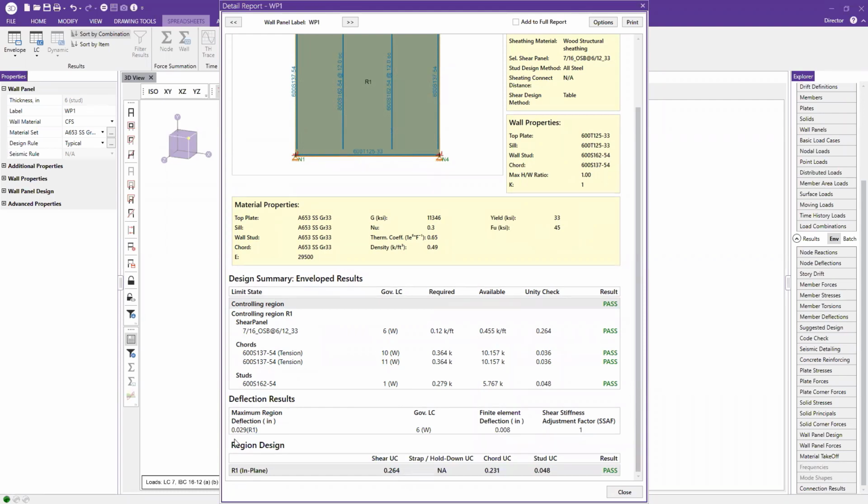As I mentioned, there's 2 types of deflection. So in this model, this is the hand calc method. We're seeing this is going to be 0.029 inches of deflection. That's substantially larger than our finite element deflection. We have a shear stiffness adjustment, so we could soften this wall so that this number gets closer to this number. In the simple wall, I wouldn't really care about it because I'd probably just think about it in this manner. But as I mentioned, when we get to a bigger model, it might make more sense. So I'll show you that here in a second, where you can adjust that.